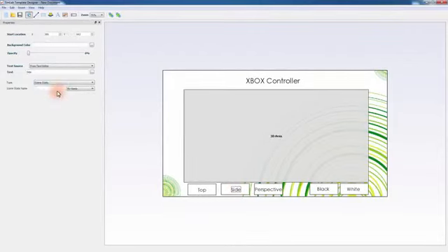Click on Save Current Settings as default, and click on Export 3D PDF. Set the path and the name of the PDF and click Save. In the Scene States Manager window, you can determine which scene states to export along with the PDF document. Keep them all checked and click OK. Clicking any button will activate the scene state connected to that button.